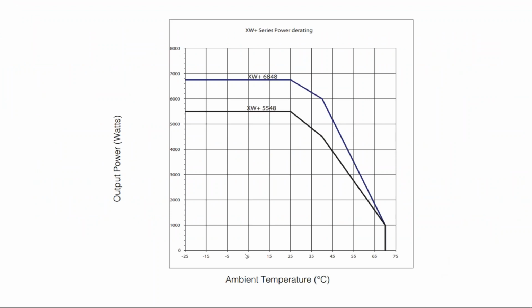So then we get into temperature control. And this is a little bit more controversial because lead acid can take a wider temperature range than lithium ion. I delivered some batteries to a site in Mississippi the other day, and it started to dip below freezing. We hadn't turned the system on yet, didn't have our heaters running yet. So the question is, are the batteries going to freeze? Well, the electrolyte inside the battery is a little bit like salt water, where they're not going to freeze at 32.